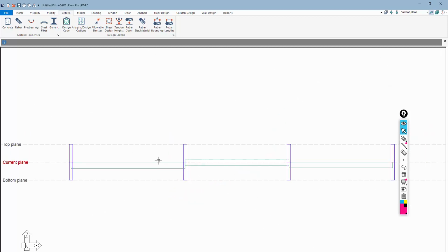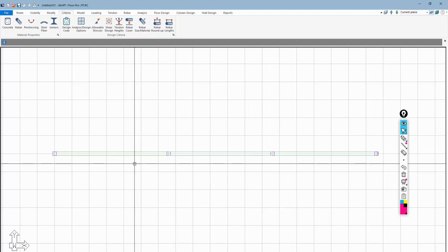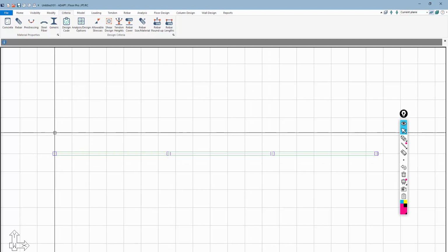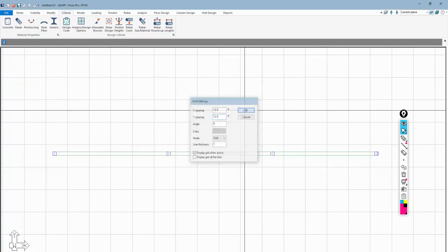The next thing, I want to add the slabs or the flange. So to model this, I want to be back not in the ZX plane, I want to be back in the XY plane. I'll just flip this back here to top view. I'm back in that top view. And if I turn on my grid again, we want to have a 28 or let's say a 300 inch flange. And so we want the grid setting to be basically 300 over 2. So 150 inches, if we convert that to feet, we want the grid to be 12.5 feet. And we're going to just set this to 12.5 here. This will make things hopefully a little bit easier.